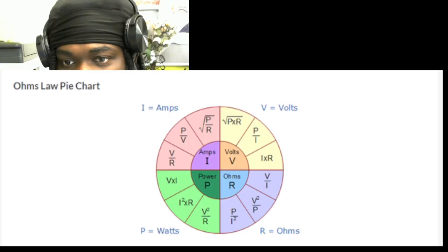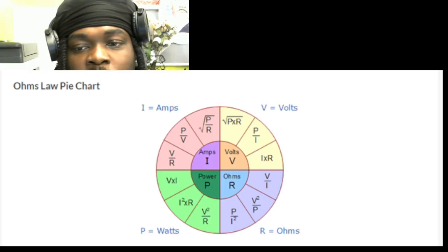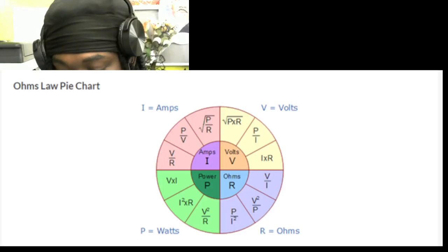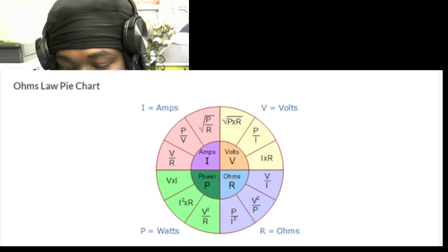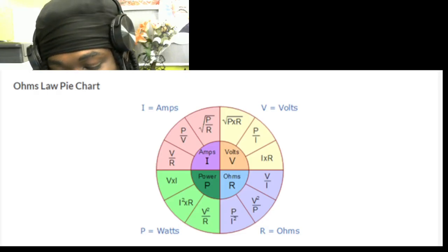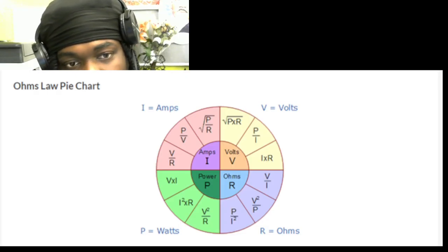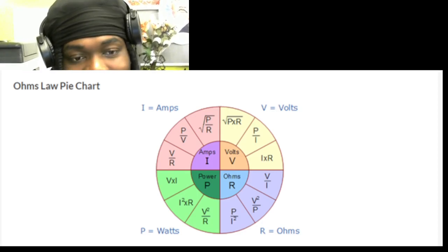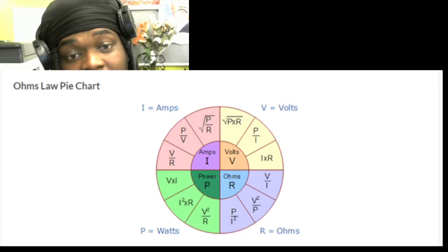So we know that we have our voltage, we have our total resistance, we have everything here, right? So now we're deciding what it is necessarily that I have to do to find the power in watts. Well, remember our IT value, which was 3.61 milliamps or 0.00361 amps, is essentially what's fueling this formula.